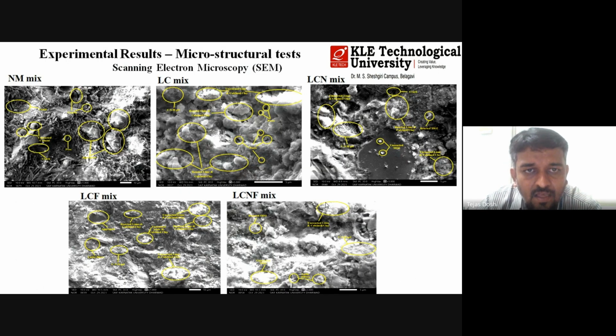penetration. Here I have the graphs related to all the mixes with respect to scanning electron microscopy. So SEM images show the interaction of different materials and their reaction with each other. Here the unreacted samples, reacted samples, CSH gels, pores, cracks, lathe fibers, and nanomaterials are all indicated in the form of images through scanning through the microscope. And this indicates the proper mixture of the materials.